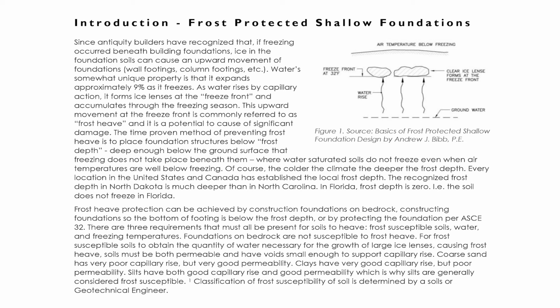If insulation is placed on the vertical outside face of the foundation structure, the passage of the heat away from the foundations can be minimized, and placement of a horizontal layer of insulation on the soil outside of the foundation structure provides even more attenuation of the heat loss. So in other words, just like we talked about with the wing insulation. But there's been some experimentation that allows decreased frost depth to be determined through the ASCE 32-01, and we're going to talk about that here momentarily.